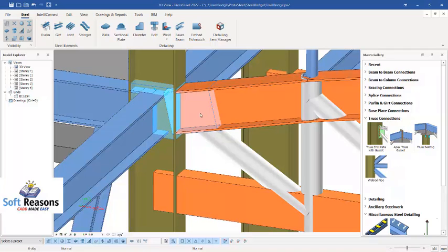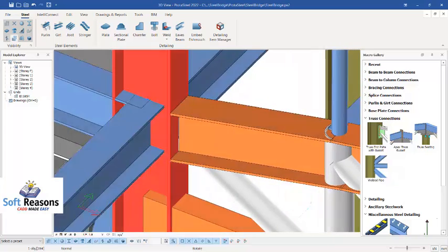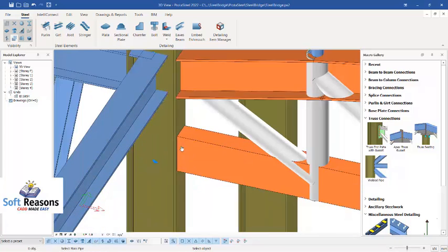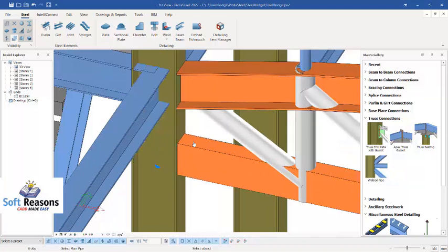The auxiliary members right there, you can always select this provision to get rid of that. So you can see how modern this is now. Okay, in this end, for this one we can still use the same method, which is this and this. If you do this now, you can see it's been trimmed and welded successfully, but I think this may not be that strong.